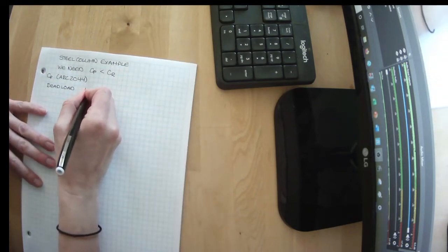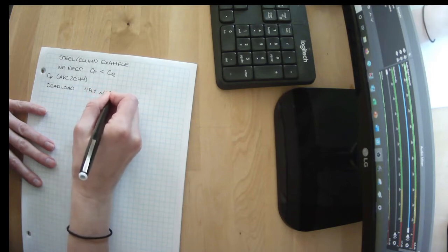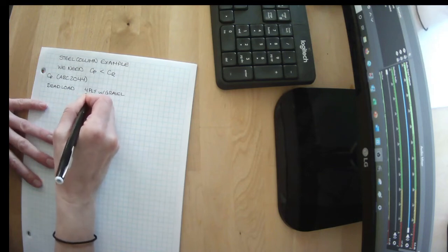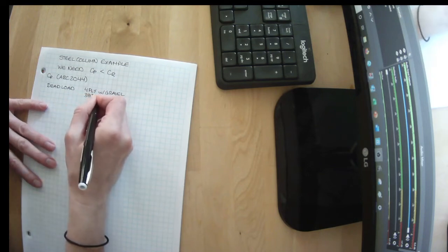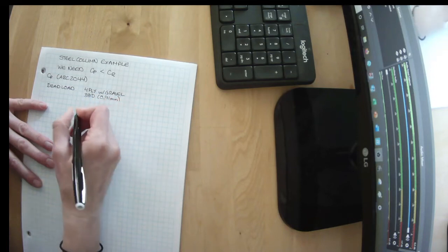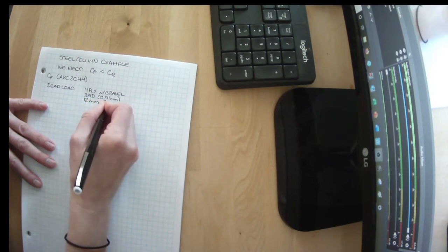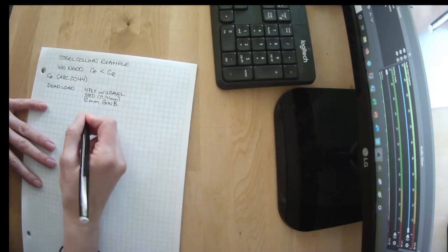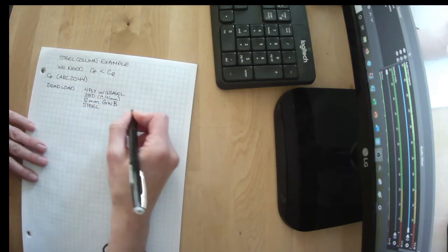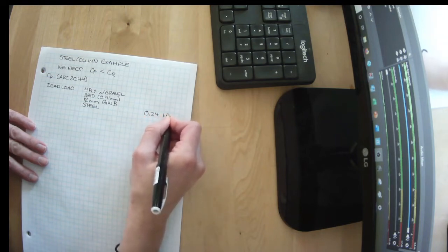They said there was 4-ply with gravel. They said there was 38 deck. They did tell us that it was 0.91 millimeters thick. 12 millimeters of gypsum wallboard soffit. And they gave us an allowance for steel. That one they gave us is 0.24 kPa.